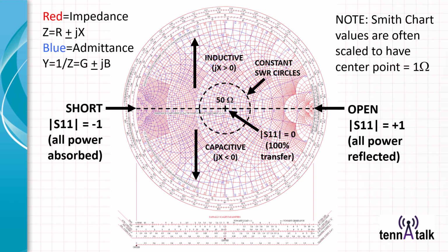And speaking of the Smith chart, here we go. If you look at the equator here, that's pure resistance. In the middle is 50 ohms. And this is the circle of SWR of 1.5, for example. Here's my 50 ohm sweet spot. No reactance. It's neither above or below the equator.